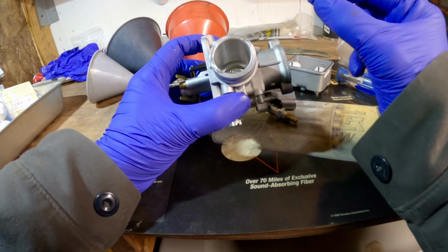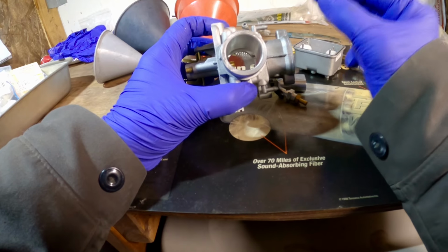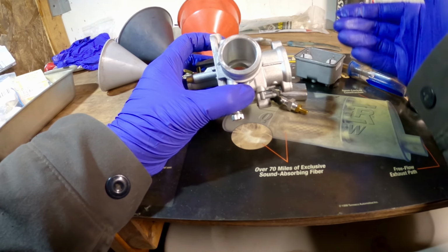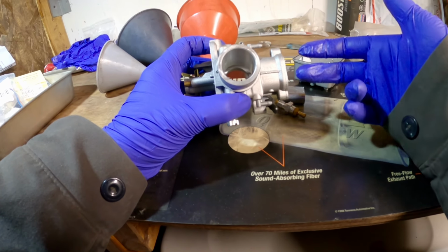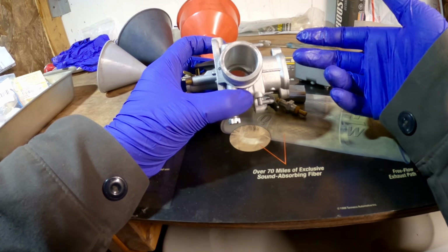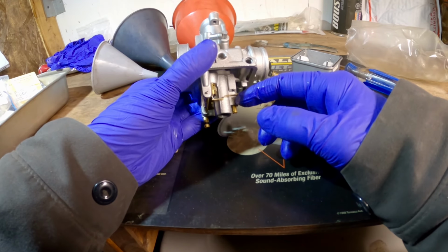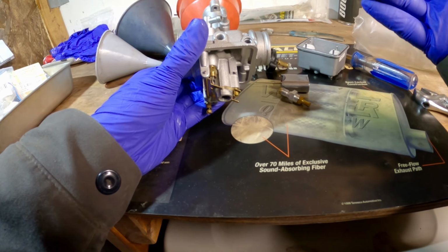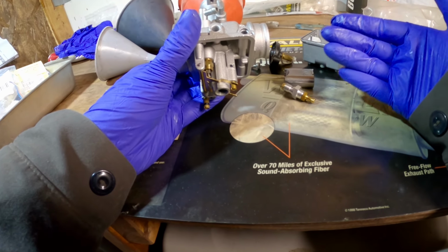And you don't need to worry about that. Again, we're going to get 80% there, and 80% is a passing grade. So quit worrying about that stuff. As you get used to the pilot main needle tuning, then you can get more advanced as you want to optimize it more. And there's other considerations like float level and things like that, but this is a 101 beginner series, so I don't want to create confusion for you.